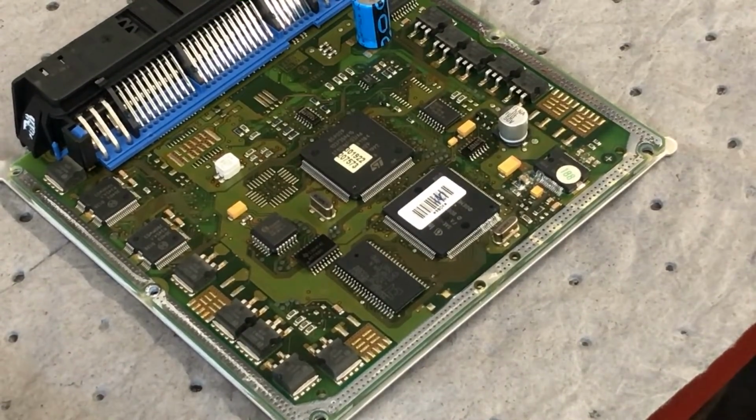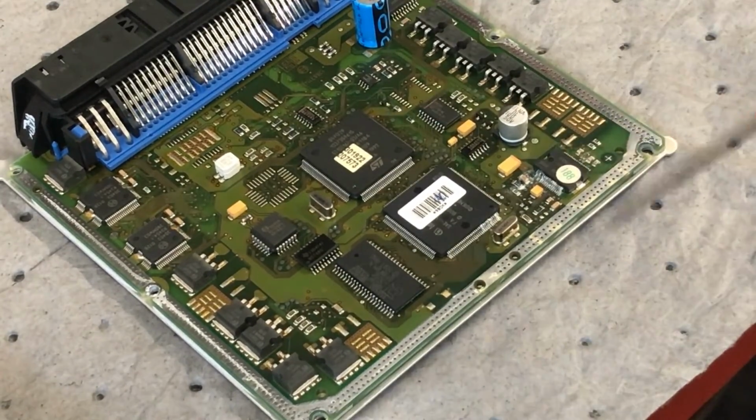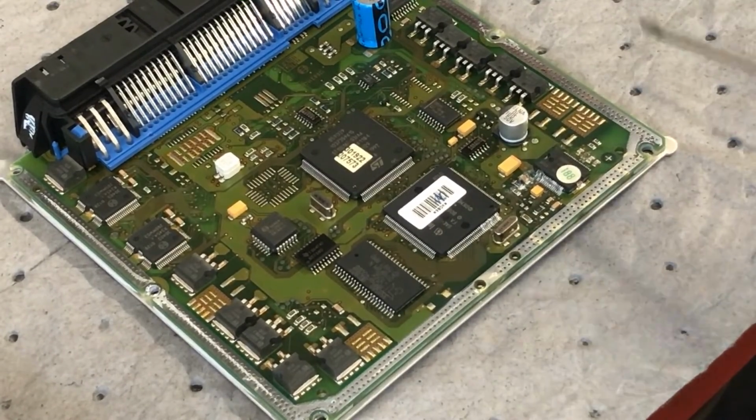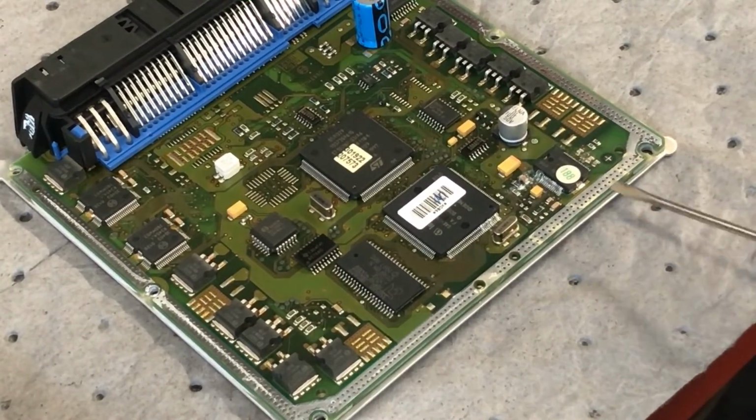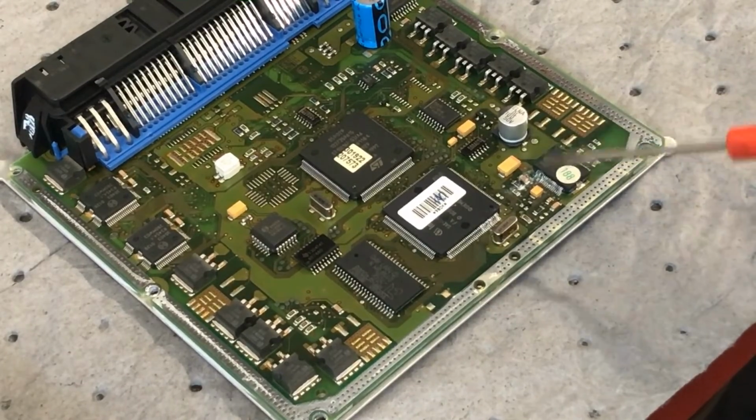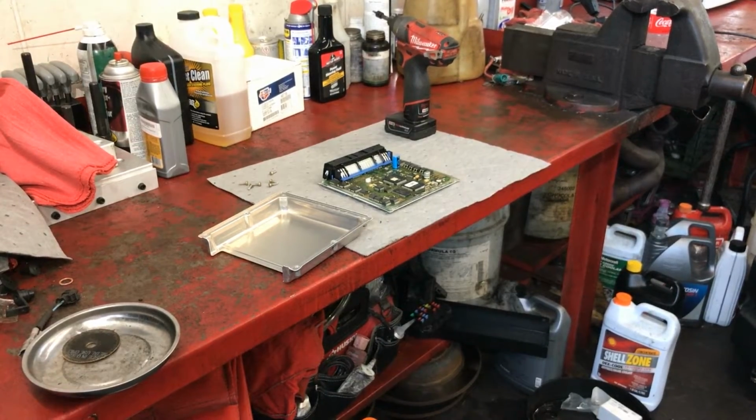So definitely this is an engine computer, and obviously being a Mercedes, it's going to be expensive. So my goal is to take this to my bench at home, do a thorough inspection, and try an ultrasonic cleaner. I'm going to put some flux around, heat the board up, and do an ultrasonic cleaning, then measure the resistors and the capacitors.